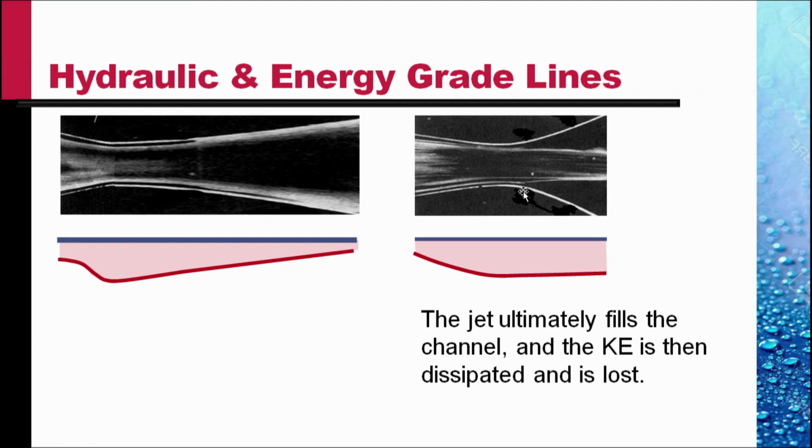As the flow travels downstream, the velocity increases, and so the pressure decreases. And then, after the throat, since the area is increasing, the velocity decreases and the pressure increases.